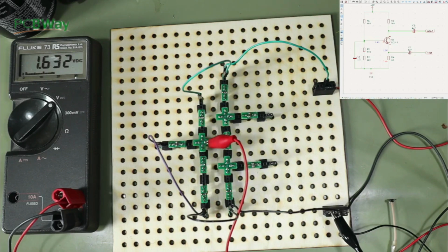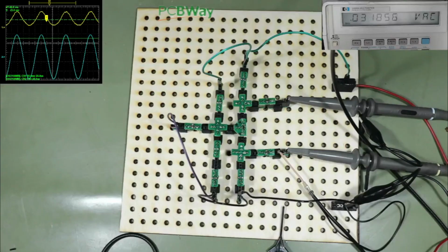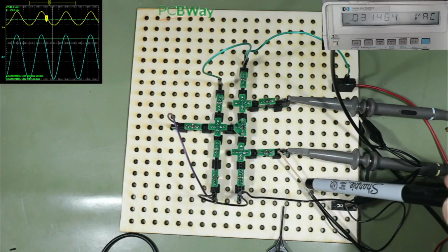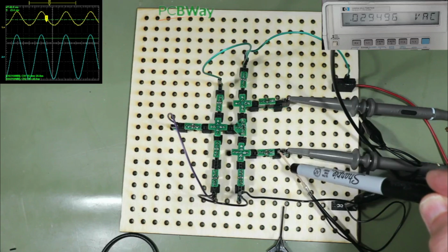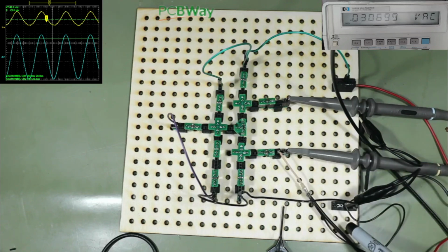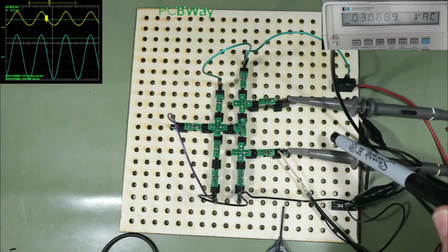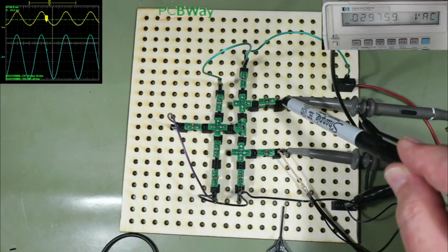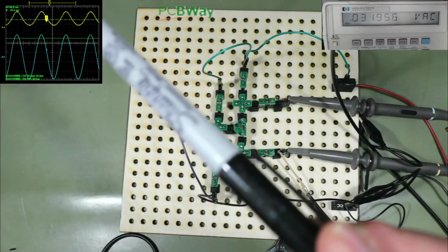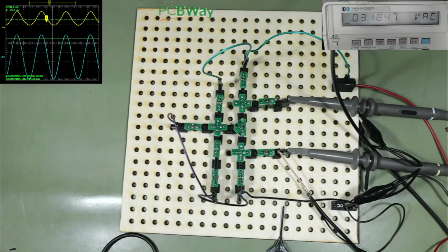Next thing to do is have a look at what the AC signal does and talk a bit more about the circuit. Right, let's have a look at the AC characteristics. I have a signal coming in from my oscillator, set to 10 kilohertz, ground going to 0 volts. We have the yellow trace on the input, the blue trace on the output, and as you can see up there, the input is smaller than the output, so we have gain.